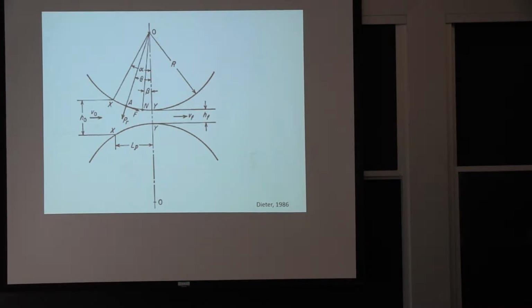The other reason why we do it this way is as you get thinner, you have more surface per volume exposed for the radiation loss of heat. So if you don't want to heat up your parts, you need to continue to go faster and faster, otherwise they will cool down, essentially. So it can come very fast at the end, in the sense that you need guides, because if something was to fall outside the rail, it would be dangerous.